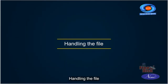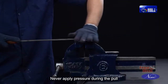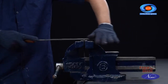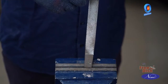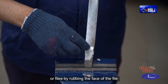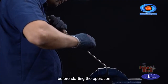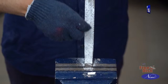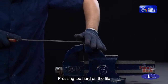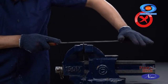Handling the file. Never apply pressure during the pull or draw stroke. Prevent pinning or clogging the file teeth with debris of files by rubbing the face of the file with chalk before starting the operation. Pressing too hard on the file also causes pinning.